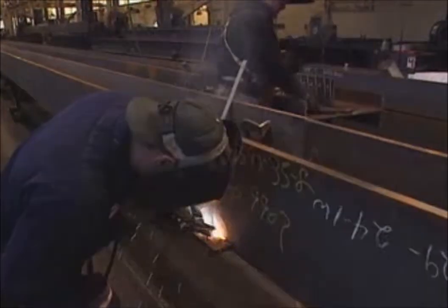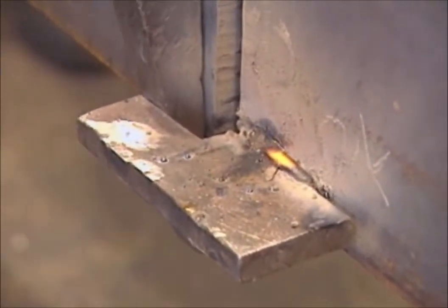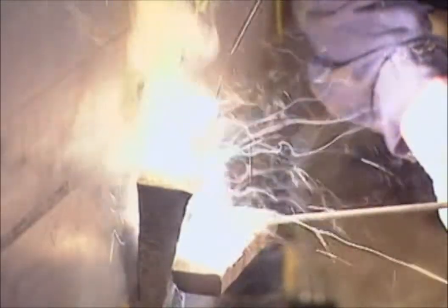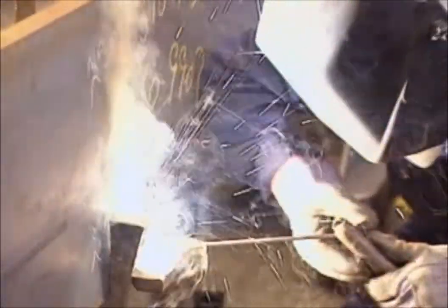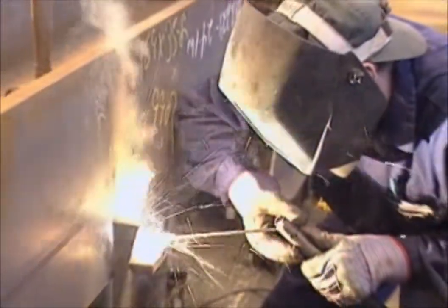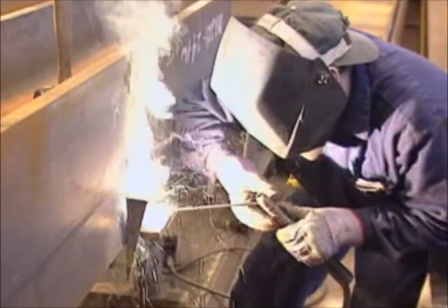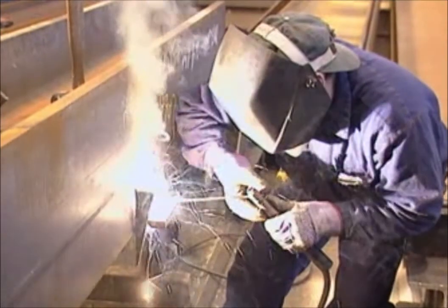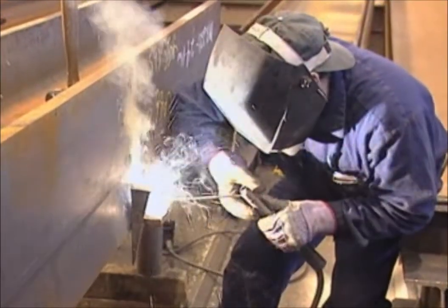In this method, the visual inspection is accomplished before, during, and after welding. In the visual inspection process, minor problems can be identified and corrected before a weld is completed. This eliminates costly repairs or rejection. Visual inspection should be used before any other non-destructive or mechanical tests are used to eliminate obvious weld problems.